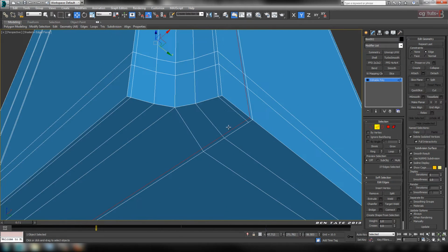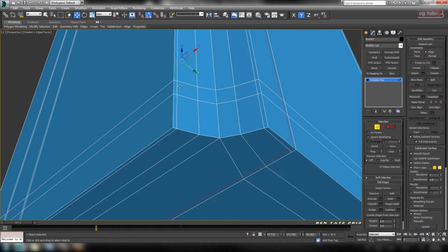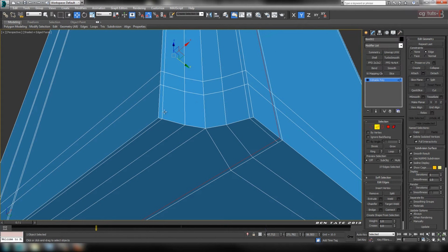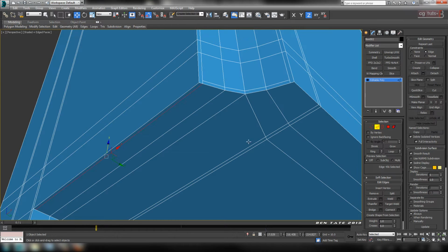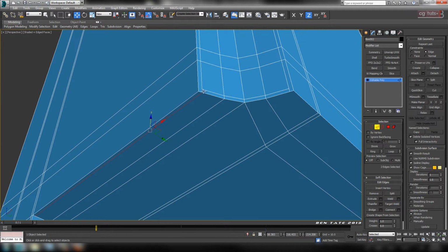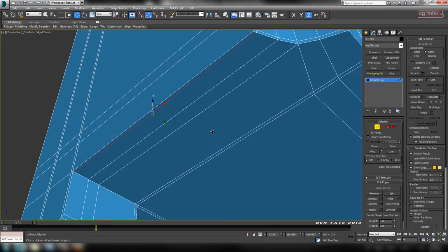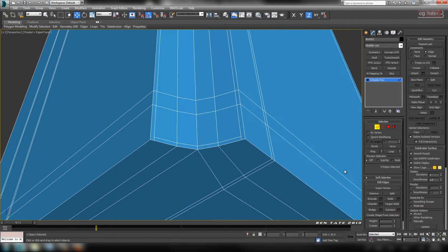Okay, now on the bottom here, we have the same issue that we had on the inside. These loops are coming down and they're going underneath, and we could probably do the same thing here to kind of contain those within this section. So let's try doing that. Let's grab these 5 edges again here on the outside. Do another connect, and we'll just slide that down, like so. And let's grab this one and the small one here, and we'll remove those edges. Control backspace. And let's get this one here. Let's do a loop on that. We'll deselect that one there. And we'll control backspace that one out as well. Okay, now we can just target one of those corners up.